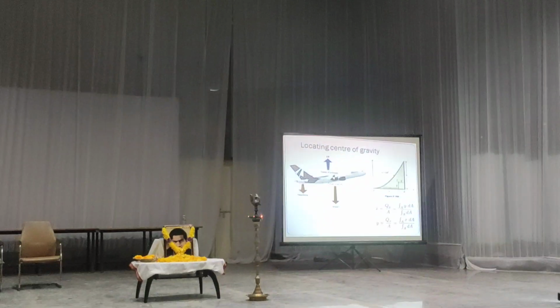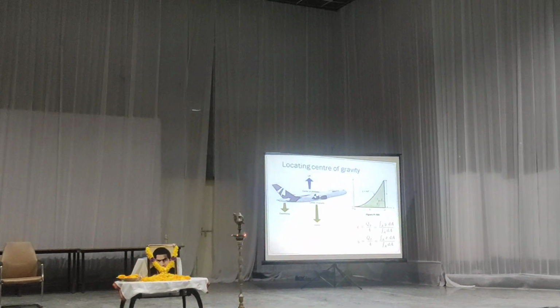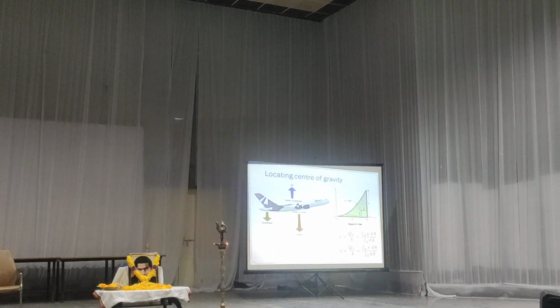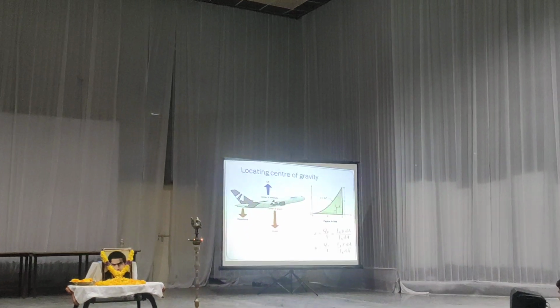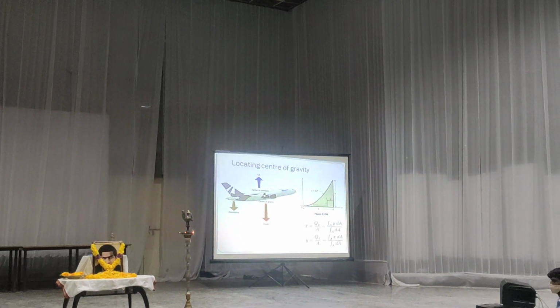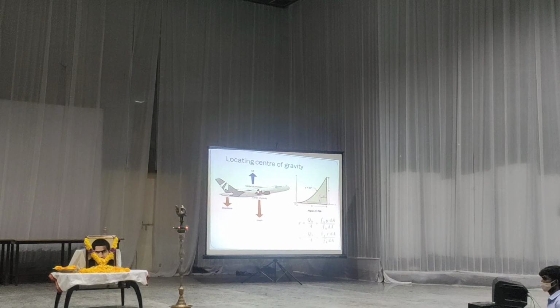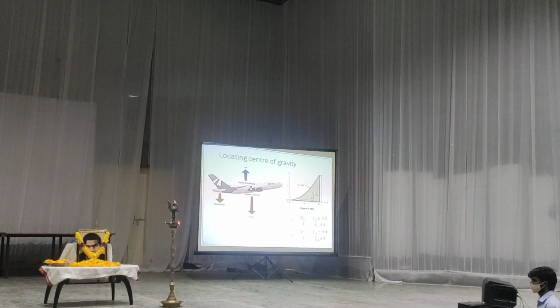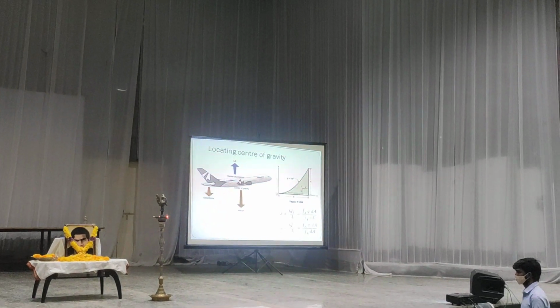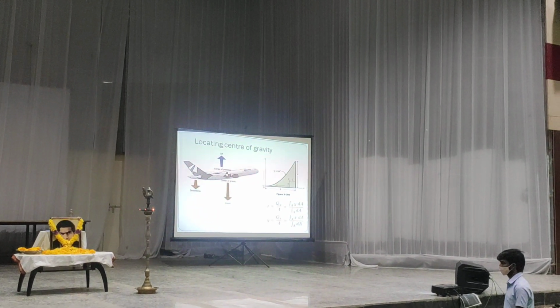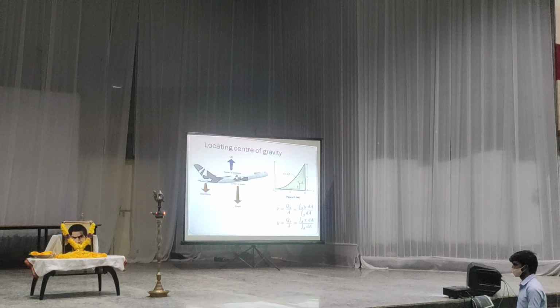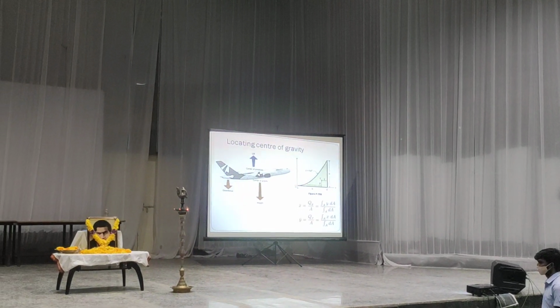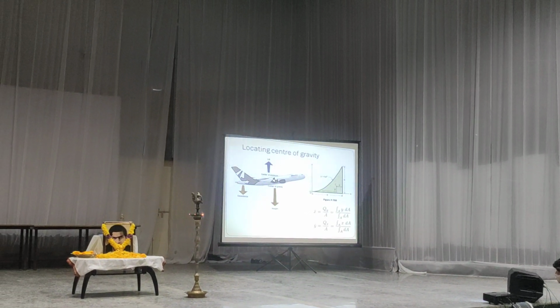Okay? So you need to integrate the variable y over the area. Then you'll get the Qy, and if you divide it with A, that is going to give you x coordinate of center of gravity. And similarly, you can calculate y coordinate of center of gravity. When you keep x comma y, that will give you the location which shows the center of gravity.